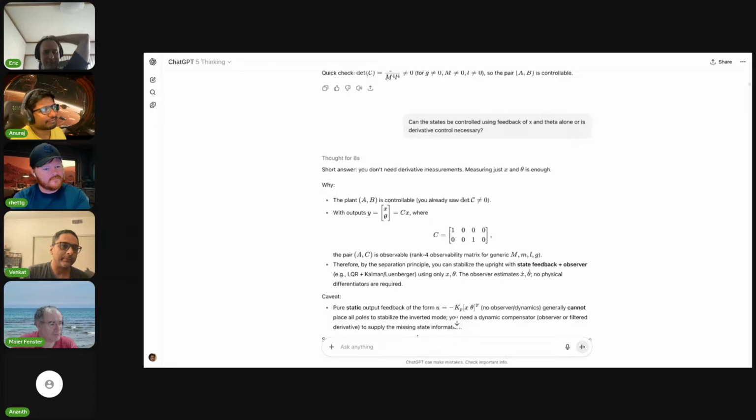But if the broomsticks are of very different lengths, so one is very long and one is very short, then you can control both with one hand. Because the long broomstick has a slower time constant, the short one has a fast time constant, and you can control one and the other one won't go totally out of control. You can get it back into control. Now, if you write the controllability matrix of this, you will notice that it drops rank when the 2 lengths are the same. You'll get some term where L minus L cancels out and some term drops to 0. So you drop rank in the controllability matrix. That's one illustration of when this kind of thing can happen.